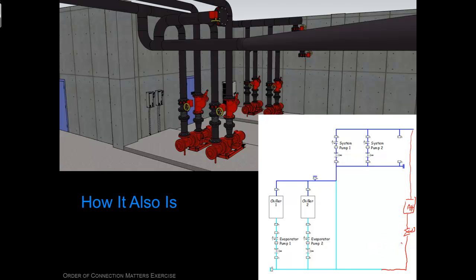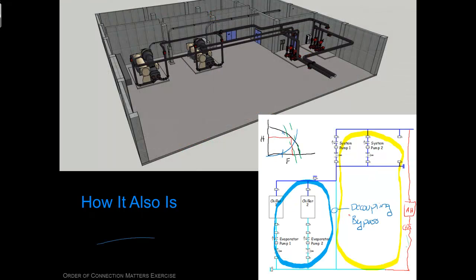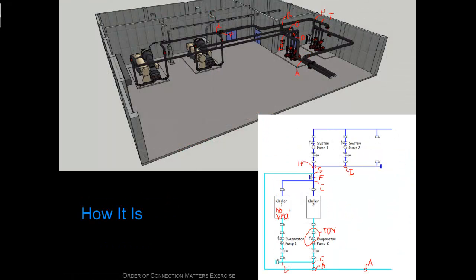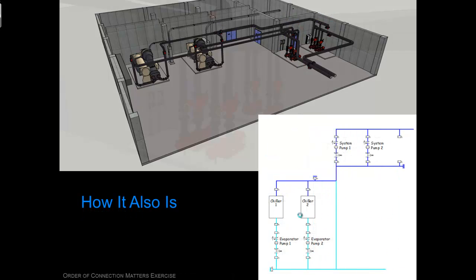And just for the sake of discussion, I'm going to stick some numbers on these. I'm going to say that this is a 500-ton plant. So at 2 GPM per ton, that means at full load there's 1,000 GPM going out to those air handlers. Each of the chillers is equally sized, so 500 GPM here, 500 GPM there. And I'm going to page up just for a minute. So that's the no VFD chiller. I just want to make a note of that.